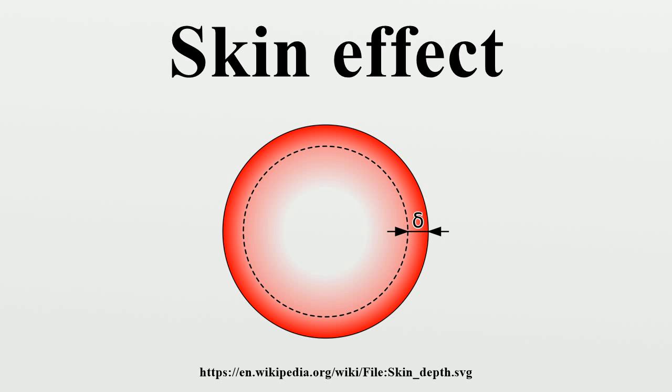At very high frequencies, the skin depth for good conductors becomes tiny. For instance, the skin depths of some common metals at a frequency of 10 GHz are less than a micrometer. Thus, at microwave frequencies, most of the current flows in an extremely thin region near the surface. Ohmic losses of waveguides at microwave frequencies are therefore only dependent on the surface coating of the material. A layer of silver 3 micrometers thick evaporated on a piece of glass is thus an excellent conductor at such frequencies. In copper, the skin depth can be seen to fall according to the square root of frequency.